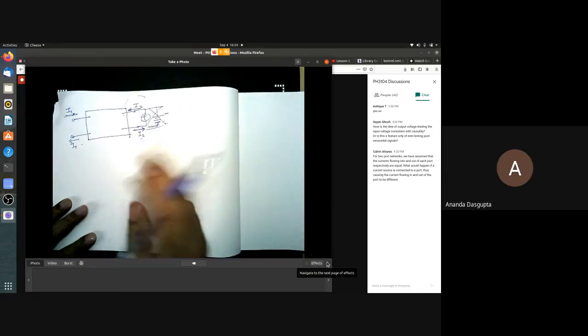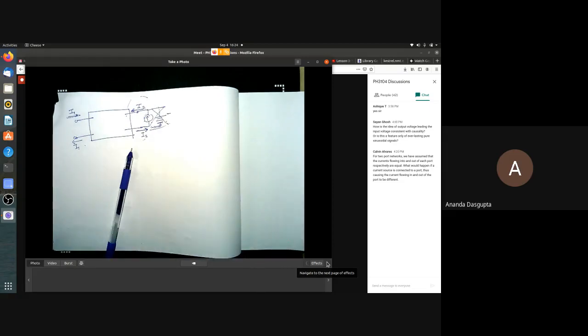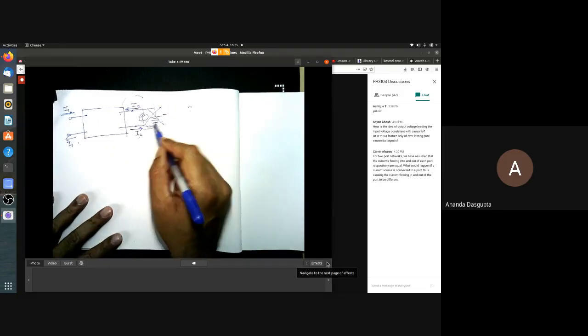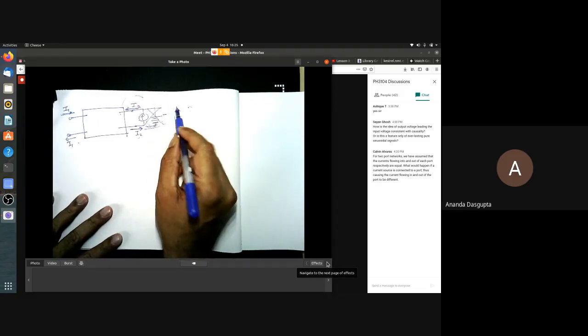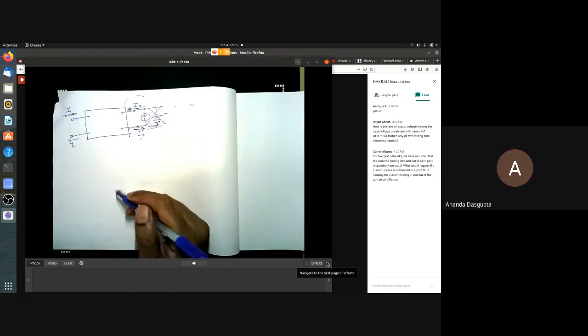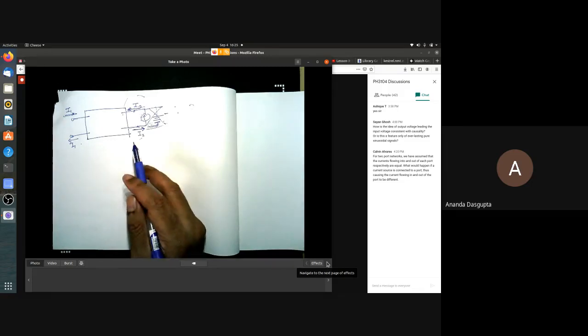After all, what do you do outside your two-port network? Your black box, something happens inside that. Then you have two terminals sticking out. What you do to those two terminals is entirely up to you. You can connect a whole mess of stuff, right? And the current can branch in various ways. But ultimately, whatever current goes out here has to come in, because that's nothing but Kirchhoff's current law, the law of conservation of charge.